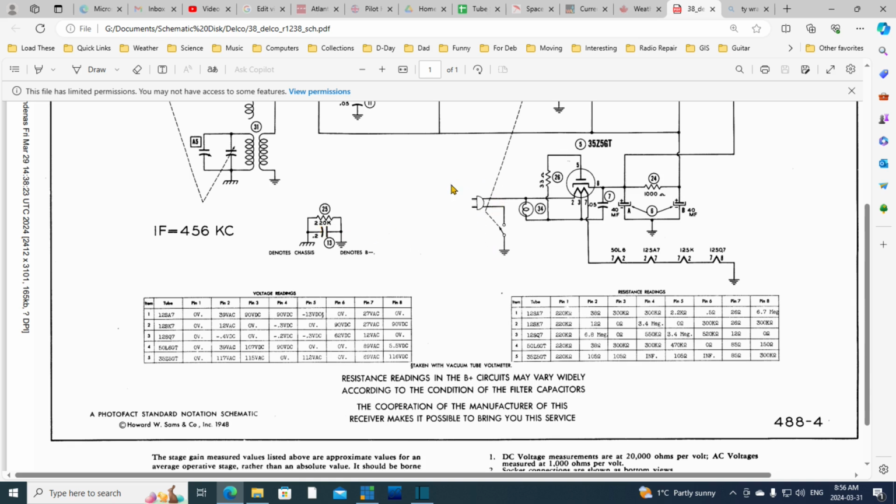In a radio of this sort, with this kind of plug, you don't know, it's 50% plugged this way, 50% plugged the other way. Half the time, the B minus is going to be at 120 volts above ground. Dangerous. And then you've got this chassis connected to it through these components. These components are good.